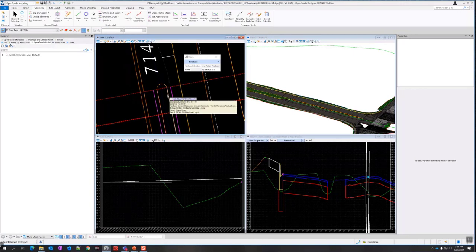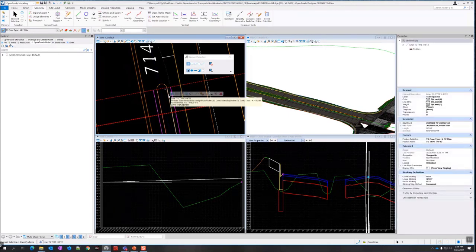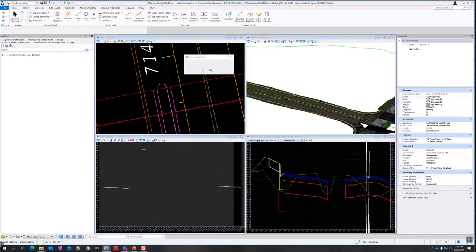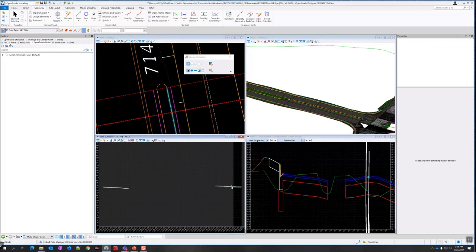And then the element to project is going to be the pavement asphalt PM, and I'm projecting it onto one of these traffic separator lines, the one that's right on top of it. And then I can verify that it's set up right by opening the profile model for each one. So this is what happens when you use the whole length.